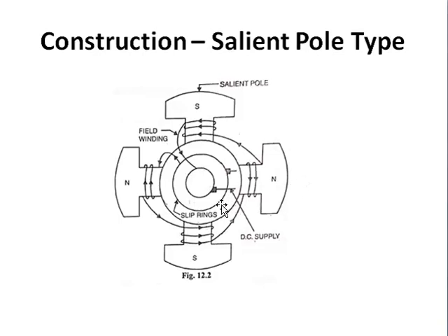For doing that, we use a pair of slip rings. So you can see here circular, this is one slip ring and this is another slip ring, and on that slip ring we have the brush. These are the carbon brushes. It is not fixed, it will be just pushing on that particular slip ring, making a firm contact with that slip ring. So here one more carbon brush we have, and this carbon brush is sitting on top of this another slip ring, and these two wires which are connected to the brush are given the DC supply.